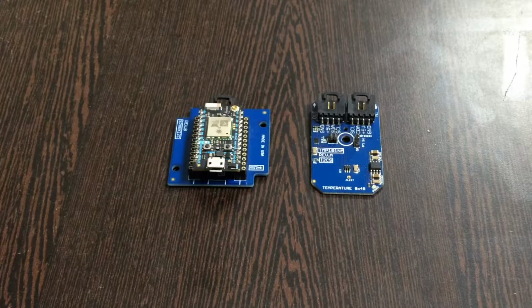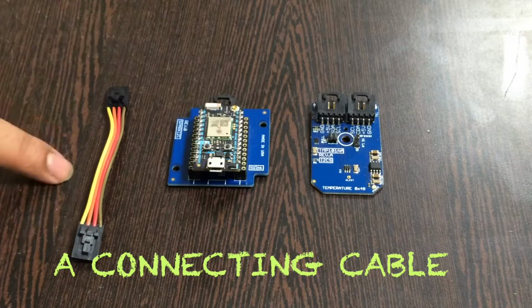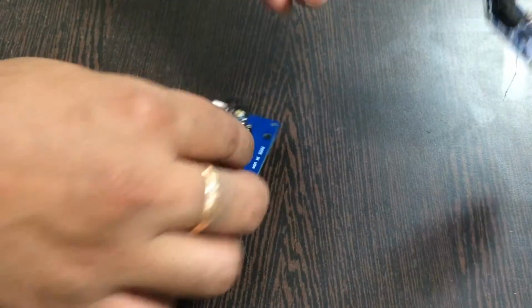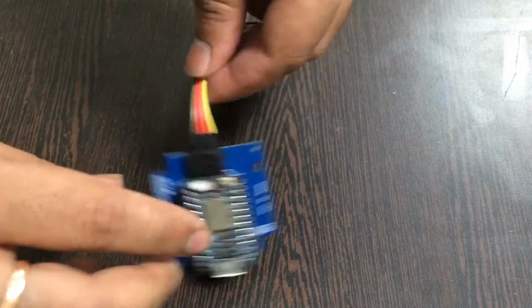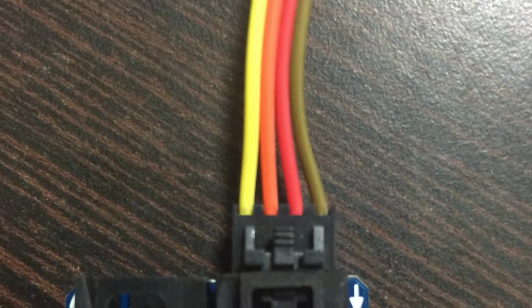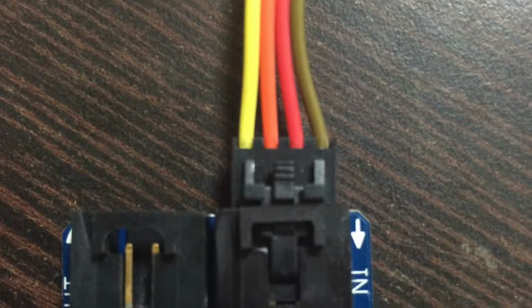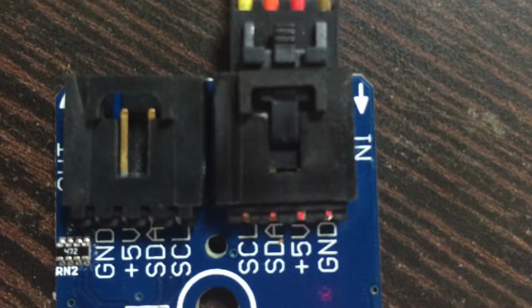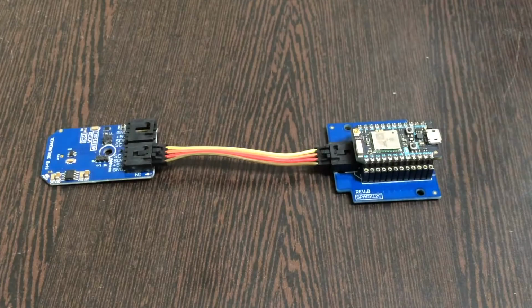Now we want to make a connection between the sensor and the I2C shield, and we need a connecting cable just like this. Gently make a connection to the sensor, and while making this connection, make sure that the brown wire of the cable is connected to the ground terminal of the sensor, and we follow this rule for the I2C shield also.